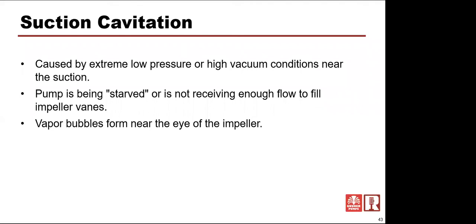So I said there's several different ways we could form cavitation in a pump. There's two major ways, the first being suction cavitation, and this is caused by extremely low pressure, if you want to call it high vacuum, that's fine, conditions near the suction. We don't have enough pressure of that fluid coming into the suction line to be able to fill all of those vanes as this pump rotates. And the pump is being starved. It's not receiving enough flow to fill all those vanes.